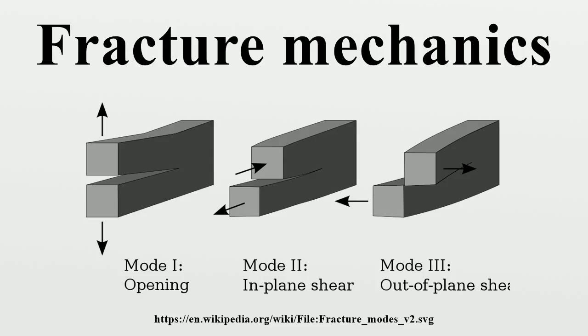The size and shape of the plastic zone may change as the applied load is increased and also as the crack length increases. Therefore, a more general theory of crack growth is needed for elastic plastic materials that can account for the local conditions for initial crack growth, which include the nucleation, growth, and coalescence of voids or decohesion at a crack tip, and a global energy balance criterion for further crack growth and unstable fracture.